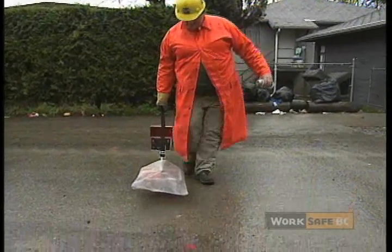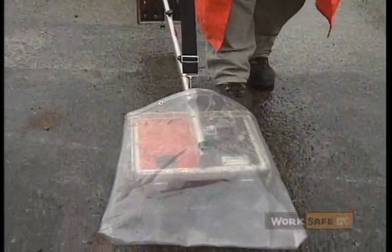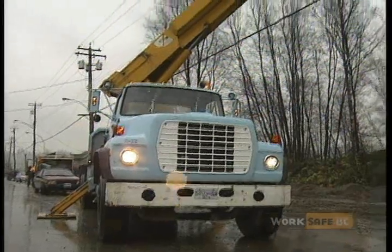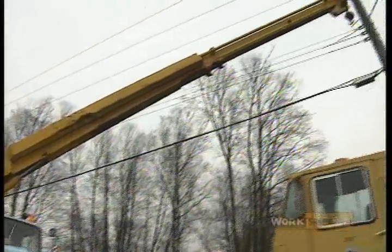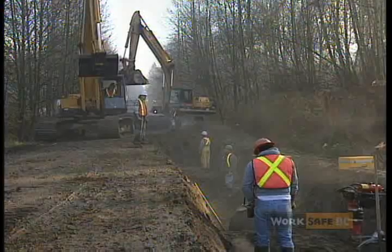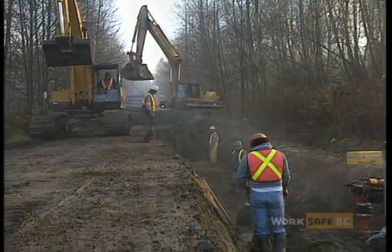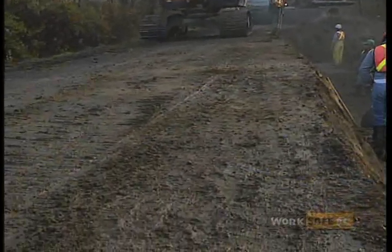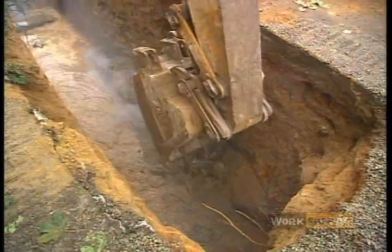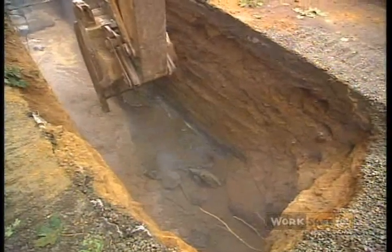Pointed tools must not be used for probing to locate underground gas lines or electrical facilities. Trees, utility poles, rocks, or similar objects in the vicinity must be secured or removed, and a clean, level area extending 2 feet back from the edge of an excavation must be maintained. The side of the excavation must be trimmed or scaled to remove any loose material or rocks.